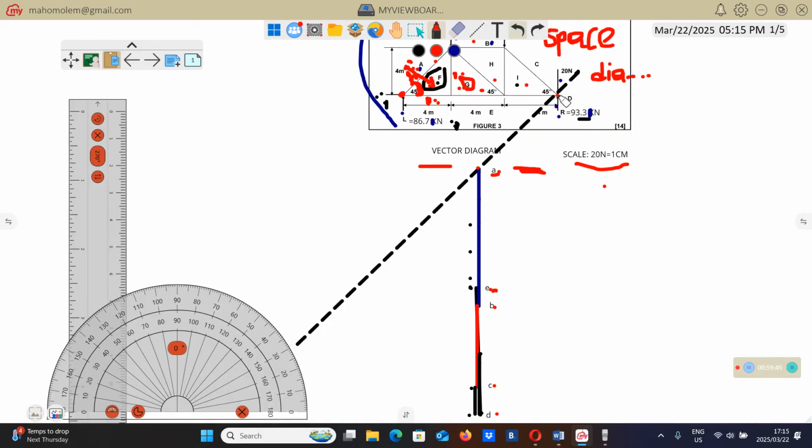But when we're going to draw a line parallel to this, we're going to measure your angle from the left hand side. So you'll put your protractor like this and measure 45 from here. You'll have 0 here, 10, 20, and so on. 45 will be there. You will measure from this side in this case, because this 45 is measured from the left hand side of this joint.